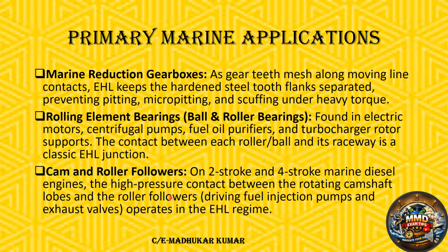So we have elastohydrodynamic lubrication over there. Okay, we have the cam and we have the roller followers. There also you will see the curved surfaces and they have the line contact. And so the EHL regime is established over there, elastohydrodynamic lubrication between the cam and rollers. Either we talk about the fuel injection, the fuel cams and rollers, or the exhaust valve, the exhaust valve cam and rollers. There we have elastohydrodynamic lubrication.